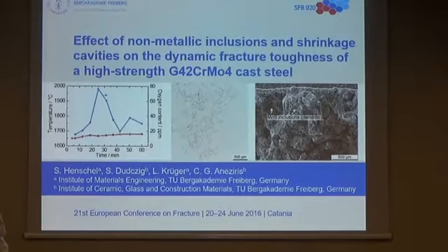So these were the aluminum oxide inclusions, and then we also measured the manganese sulfide inclusions. These have a similar diameter, but the particle distance was much lower when we compare this to the aluminum oxide inclusions. This is due to the structure of most of the manganese sulfide inclusions.